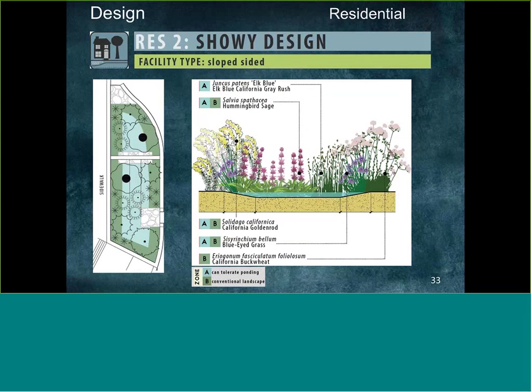And I would just point out that in these, you can see the ponding zone, that's zone A. That's the area where plant selection is specialized to bioretention. In zone B, designers can really choose what they want. So if you're on the upper side slopes of your rain garden, as long as the plant will tolerate the sandy conditions of the bioretention soil, it's really up to the designer based on the project. It's zone A down in the bottom that's much more specific to the function.